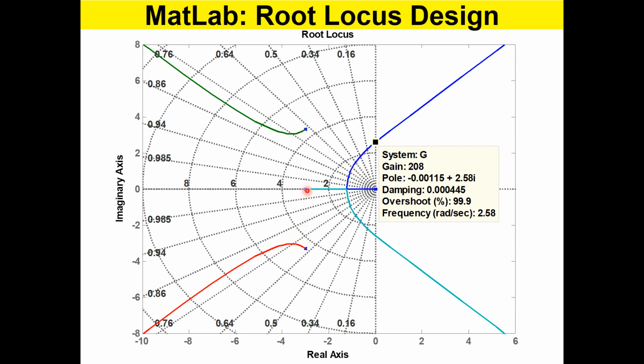So we figured out that this part on the real axis is part of the root locus. You can see the green and blue and the red, these are different poles. These two poles move head on and meet at this point, that is minus 1.3 or something, and after they split, one goes here, the other goes there.